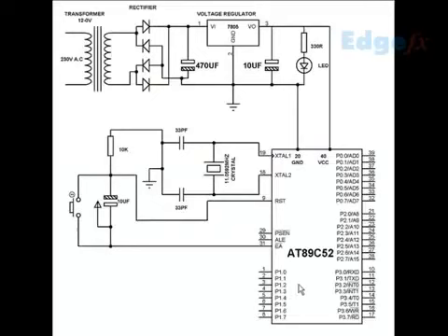For every microcontroller, whether it is 89C51, C52, or 89C2051, these are all 40 pin ICs, and those are 20 pin ICs, but in all cases we need to have certain standard connections. Standard connections are at least the power supply section, which has been separately discussed, where we have a step down transformer and then we get 12 volt AC.